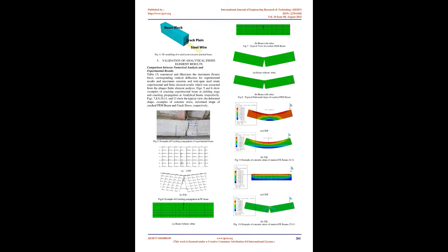Finite element model. Abaqus V6.16 computer program is applied for analyzing all tested beams by [17] and [18]. Structural components corresponding to the finite element representation, and element designations in the Abaqus program, will be presented below. Modeling of the material concrete. Abaqus contains 3 models for modeling the nonlinear behavior of concrete. The available models are the concrete damage plasticity, the concrete smeared cracking and the brittle cracking model.